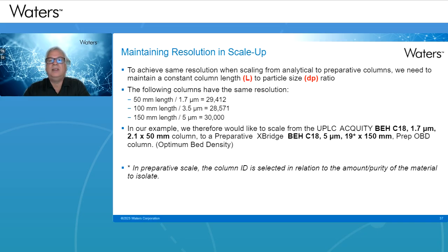And we have picked the 19 millimeter ID. This ID is selected from the limitation of the flow rate of my pump. Some pumps can go to 150 mL per minute. Some other pumps can go to only 40 mL per minute. So this is a limitation on the column dimension that we have. But again, it will still work on this one.